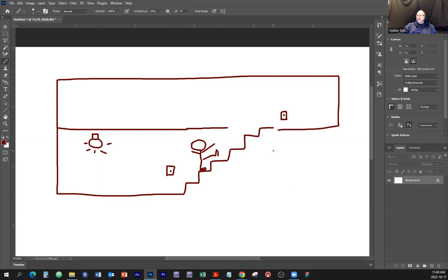Okay, you're walking up the stairs and you forgot to turn the light off. Well, if it's a three-way switch system, there is opportunity for you that you can flip this switch and turn the light off. So you can control the same light from two different switches.